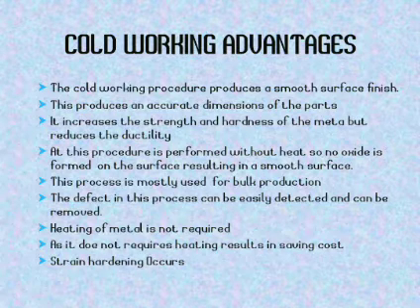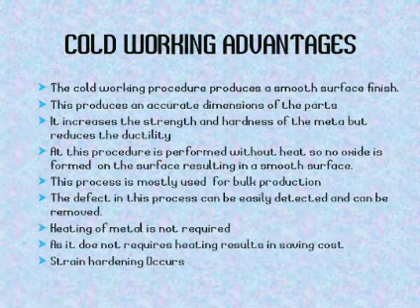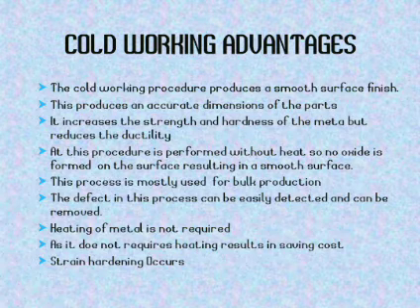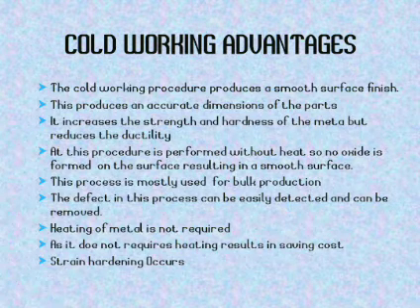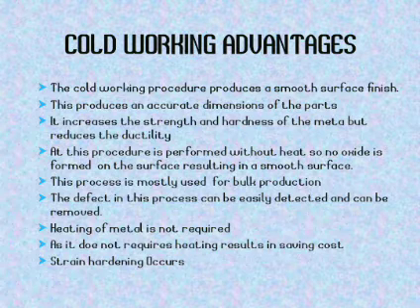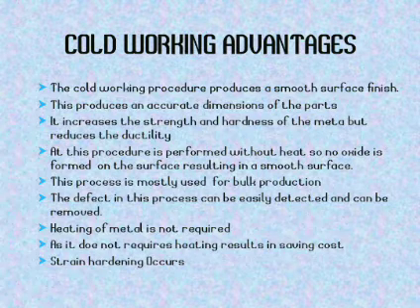This procedure is performed without heat, so no oxide is formed on the surface, resulting in a smooth surface. This process is also mostly used for bulk production, and defects in this process can be easily detected and removed. Heating of metal is not required, which results in saving cost, and strain hardening occurs.